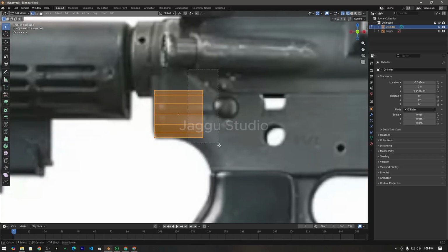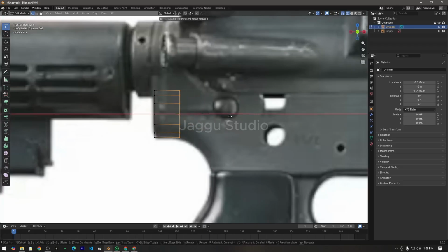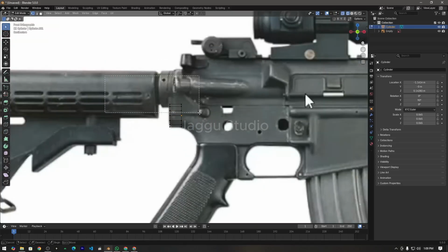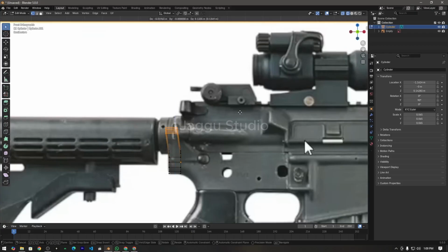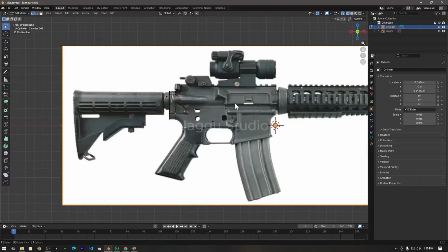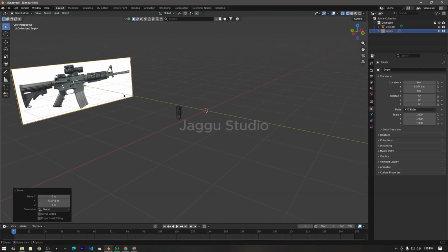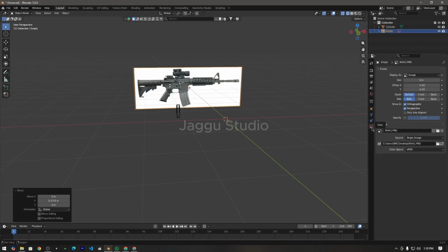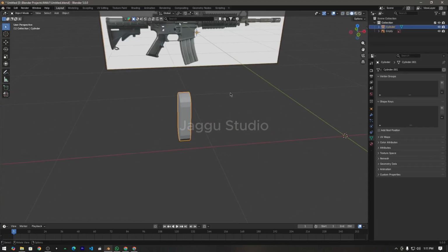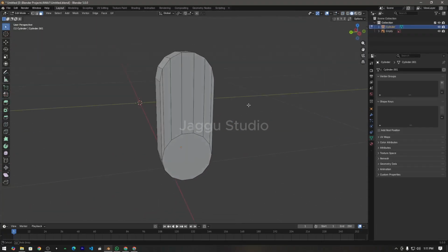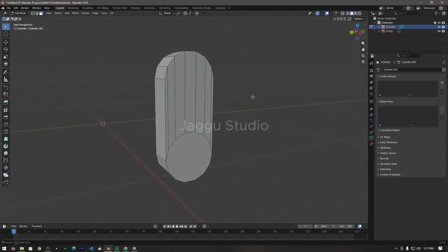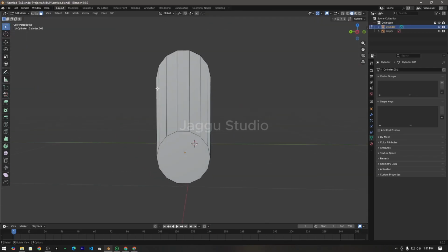and then I'm going to select these vertices, GX, and then select half of it, E to extrude it on the Z axis to somewhere around here, and then I'm going to place this reference image at the back, and then come to image data properties, check opacity and reduce the opacity. Okay, so now select this object, go into edit mode and delete the front side and the back side because we are going to fill them later.